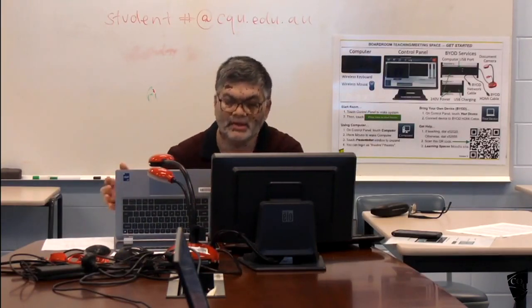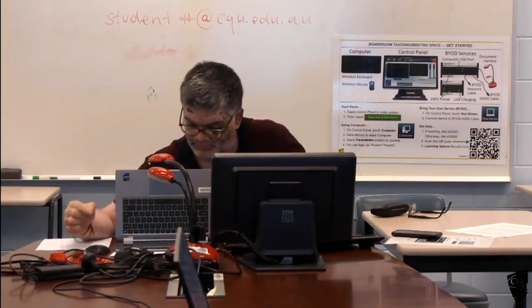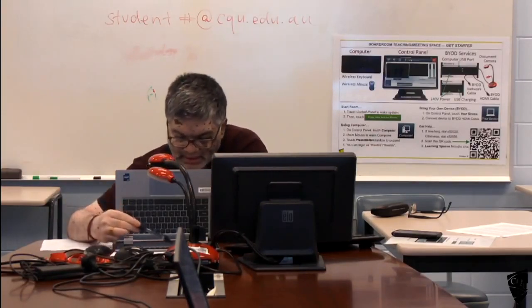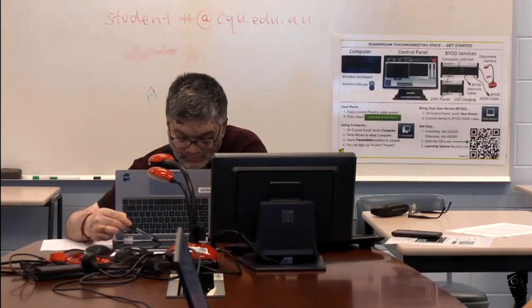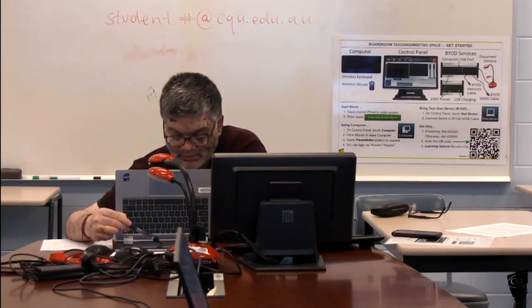So this table will tell you how much of the negative moment at the interior support, the negative moment at the exterior support, and the midspan moment goes to the column strip.